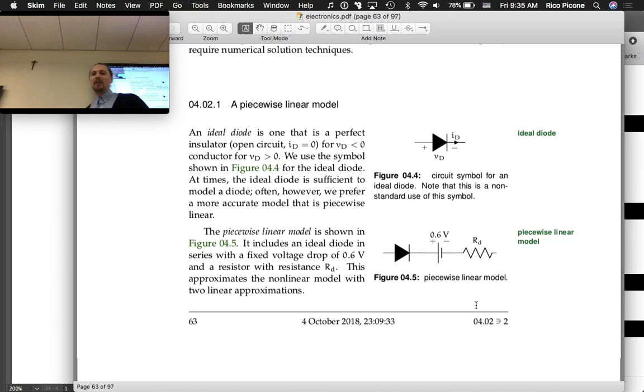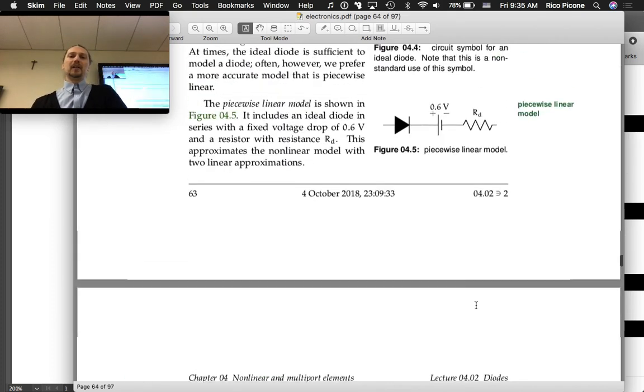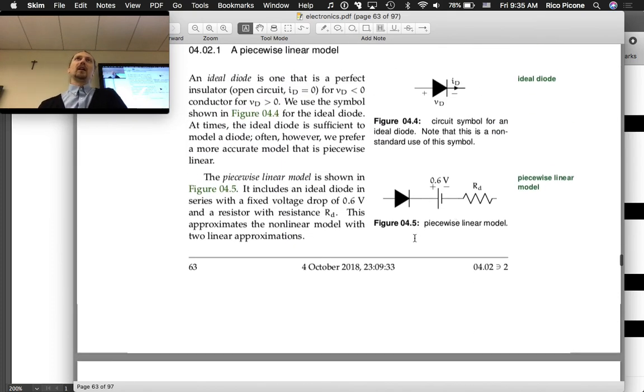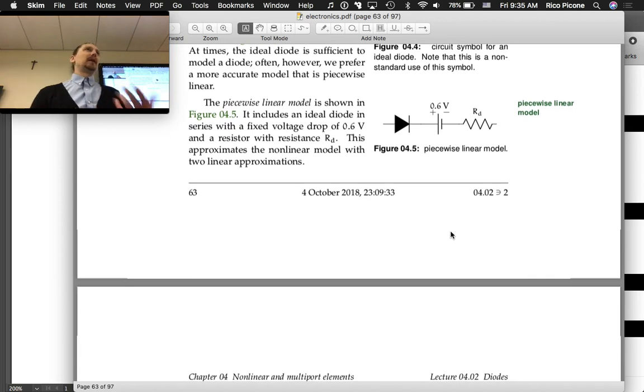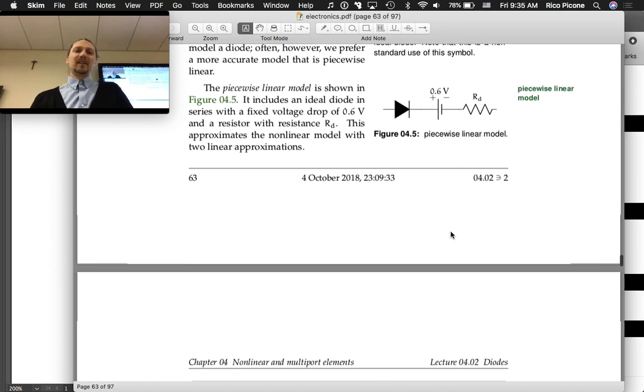So when you get above a certain voltage across it, you're going to have this linear relationship between voltage and current. And that's what we talked about at the beginning today about how to approximate RD, is we're trying to make that straight line approximate an exponential in a certain region as well as we can. It's not perfect.